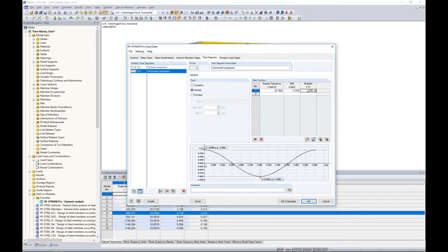So at time equals 0, this is where we're going to have 100% of that horizontal load acting on the structure. But then we move a little bit later on in time, and at about 0.06 seconds, we have 0% of that horizontal force acting. Now, that's in turn to the vertical component. We have 0% at time 0, and at time 0.06 is 100% of the vertical force acting. Now, in between this region, we're going to have some type of relationship where both forces are acting together.